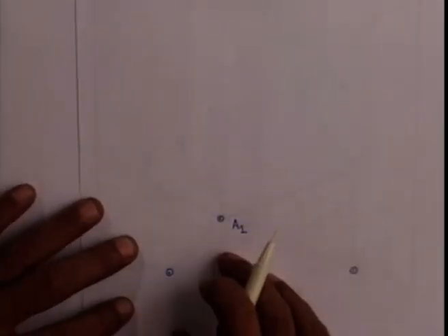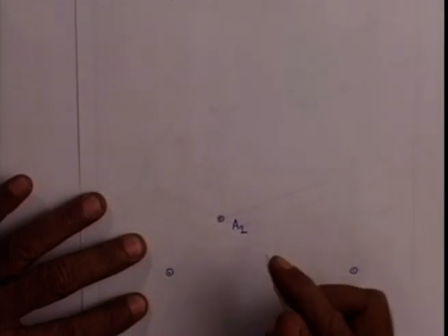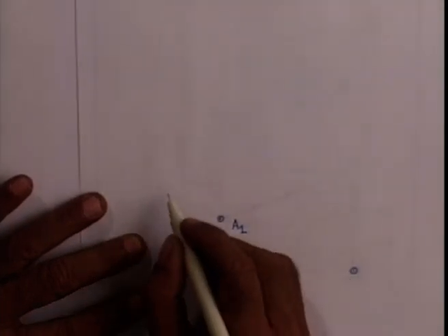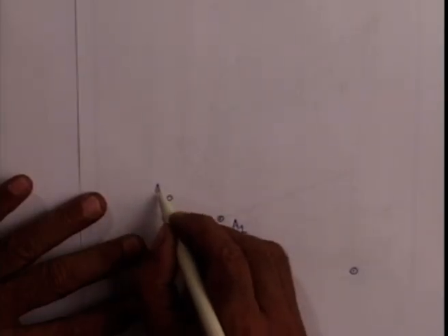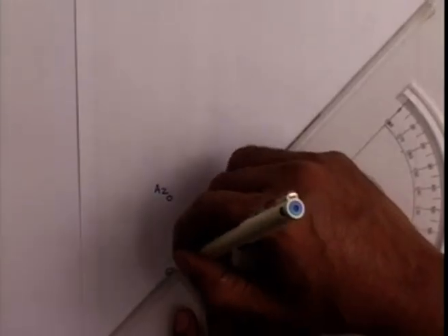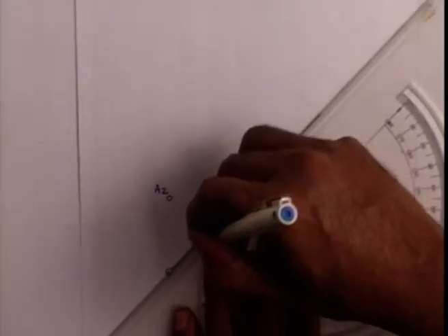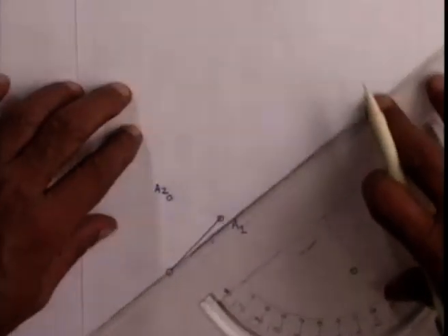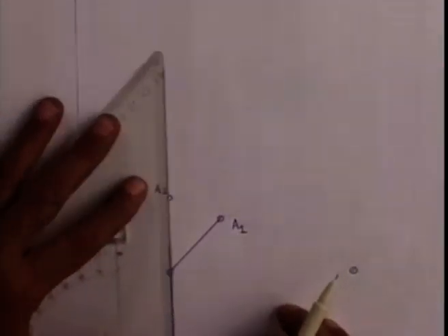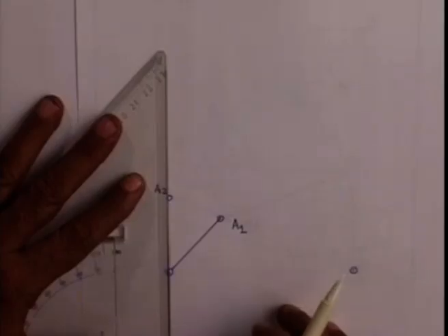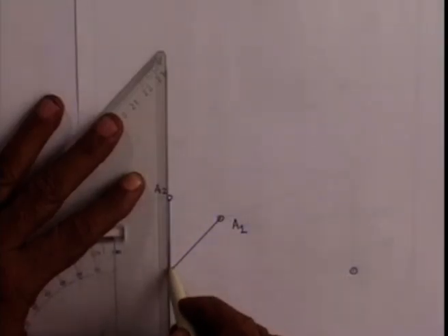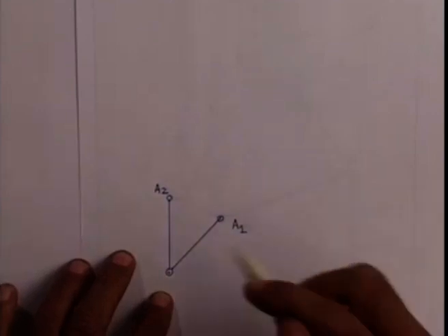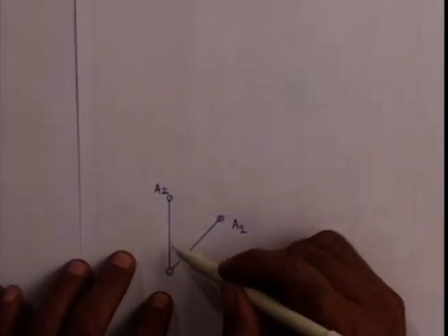Because the rotation of the input link O2A is prescribed, I can find the second position of the crank pin, which I call A2. So, the rotation of the input link from the first to the second configuration, which is given to us, is the angle between these two lines, namely O2A1 and O2A2. This is the angle of rotation theta 212.